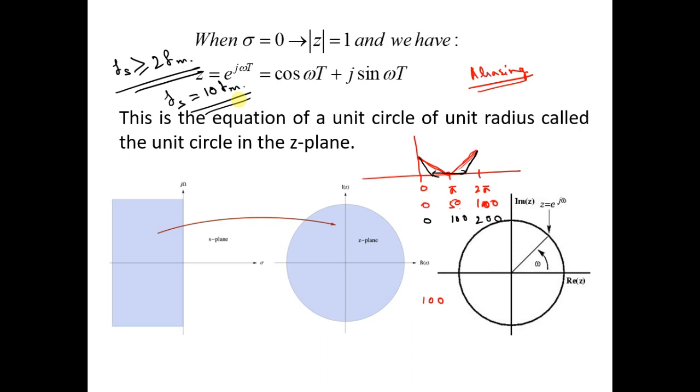There will be some aliasing incorporated into the system. Okay. So under practical considerations, we have seen that for low cost systems, Fs equals 10 of Fm.